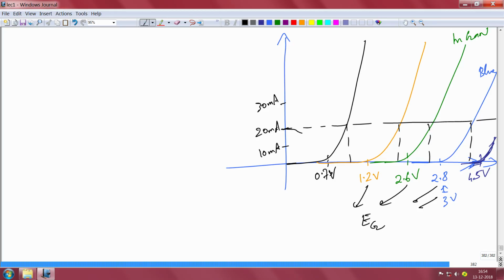What happens is that you need to spend more energy. To get the same injection current, you have to bias at a higher voltage, you are losing more, you actually have to apply more voltage. That's why you have to apply more electrical energy, that is one thing. To get a UV or a blue LED, you have to apply more electrical energy input than getting, for example, a red or an orange or yellow, right.